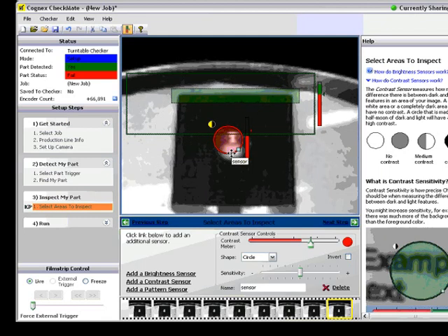We give you the ability to change from a circle to a rectangle, and that's what I'm going to do. You go on the outside corner, and you can move the region around. When you get the 4 opposing arrows, that's allowing you to move the entire sensor. When you want to adjust it again, you get the 2 opposing arrows in the corner, and that'll allow you to adjust the size of the window. So I've got it pretty much where I want it.